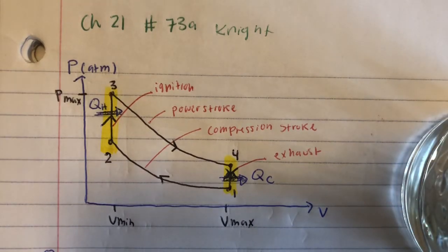The spark plug fires at point 2, releasing heat energy that can be stored in gasoline. The fuel burns so quickly that the piston doesn't have time to move, so the heating is an isochoric process. The hot, high-pressure gas then pushes the piston out toward the power stroke. Finally, an exhaust valve opens to allow the gas temperature and pressure to drop back to their initial values, starting the cycle all over again. So that just told you exactly what it's doing.